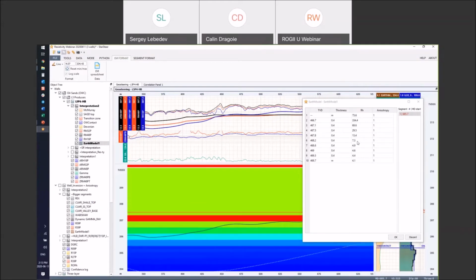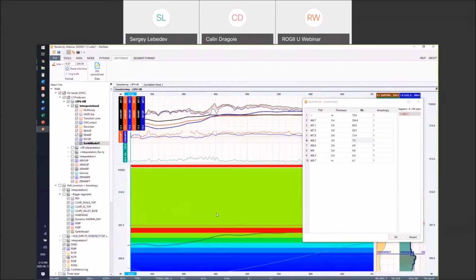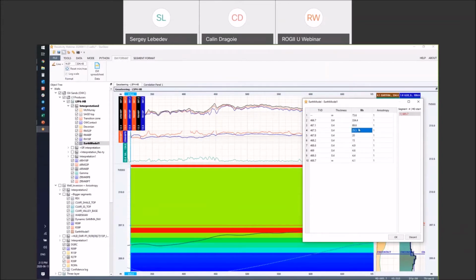So what I would do, because I already did that, and it takes some time to find the best model for you, I will just change the resistivity values here to, again, gradually increasing from 4.3, because I observed that the resistivity value in the oil-water contact was about 4.3, and then resistivity values should increase.